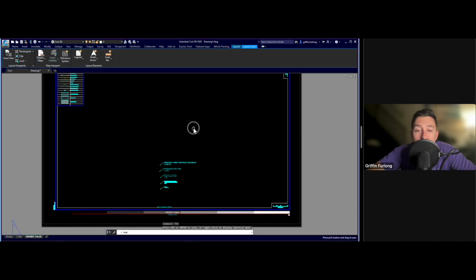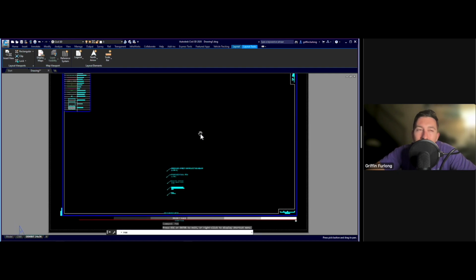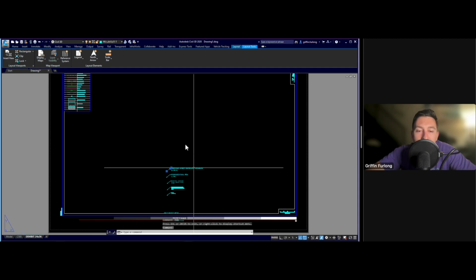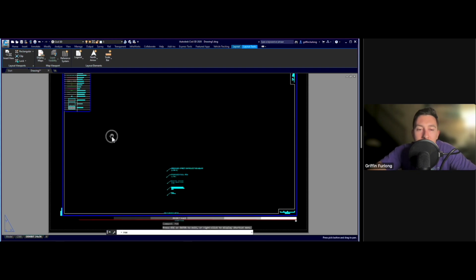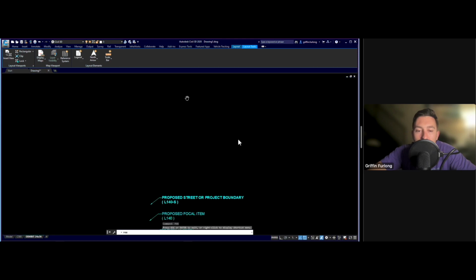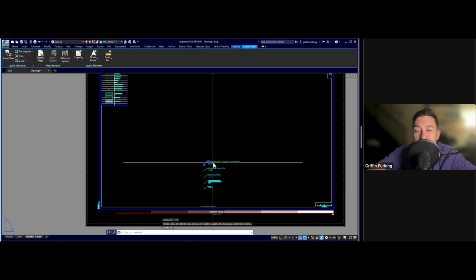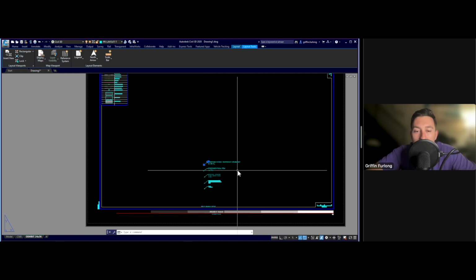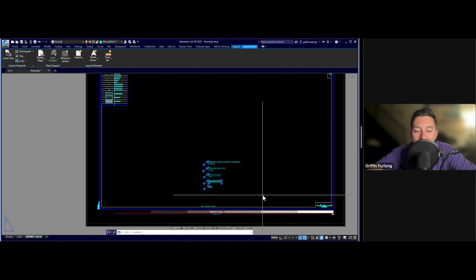I think the last thing that I'll share about paper space versus model is to be very cautious of where you're placing text. You can have text in paper space if you want, but I typically have text in paper space if it's for a legend. But if you have a whole bunch of multi-leaders that are calling certain things out, like let's say lots or roadways, I think personally that it's best to just have that right in model space. Notice that I'm able to select this and I'm in paper space, so these little text arrows are in fact in paper space. So just keep track of where your text is, and if you want to delete these, you can highlight, type in erase, or just press delete.